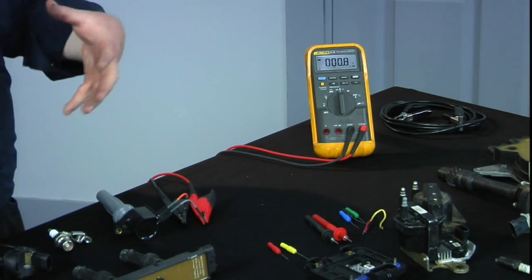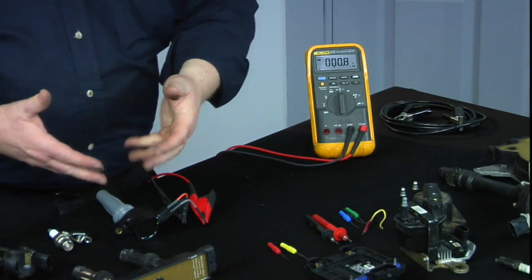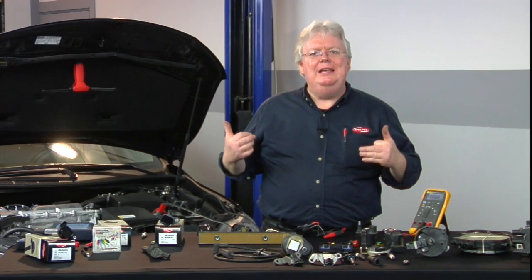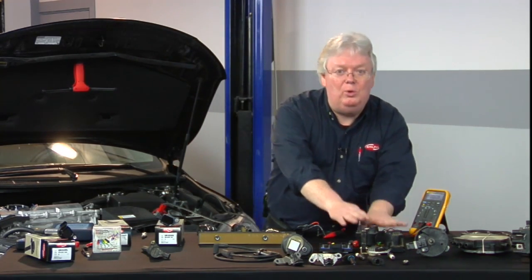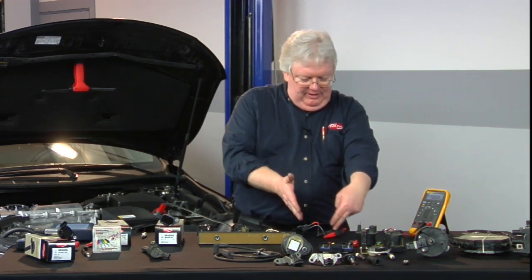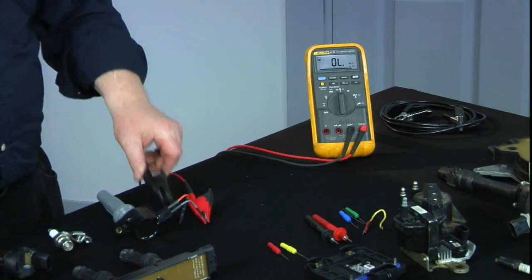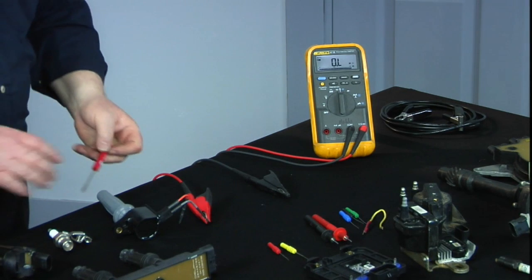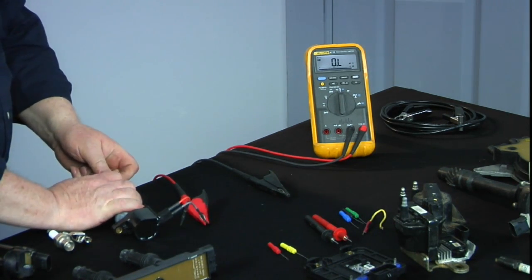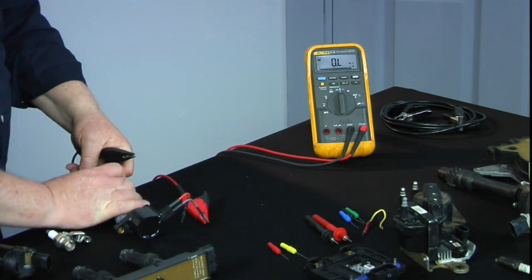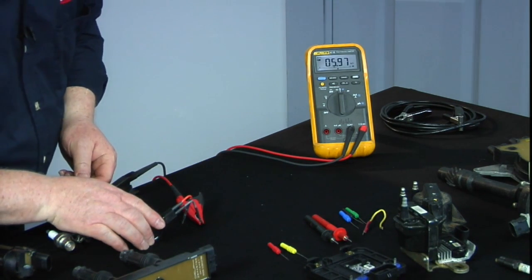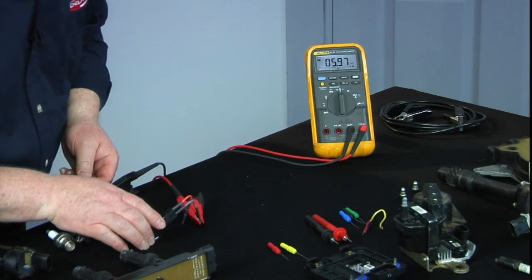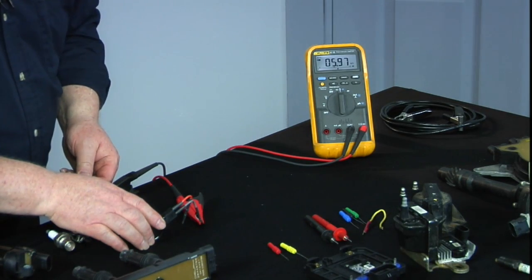So still considerable amount of current draw. That's going to really build up a field. We turn that off, and that's going to make the secondary. Now, what can we do to measure the secondary winding continuity? Same thing we did with these older coils. We can leave either one of these plugged in, unplug the other, pocket screwdriver, go into where the spark plug is going to go against the spring contact that goes into the output of the Coil-On-Plug, the C.O.P., and we've got about 6,000 ohms, 6K of resistance of the internal secondary winding.